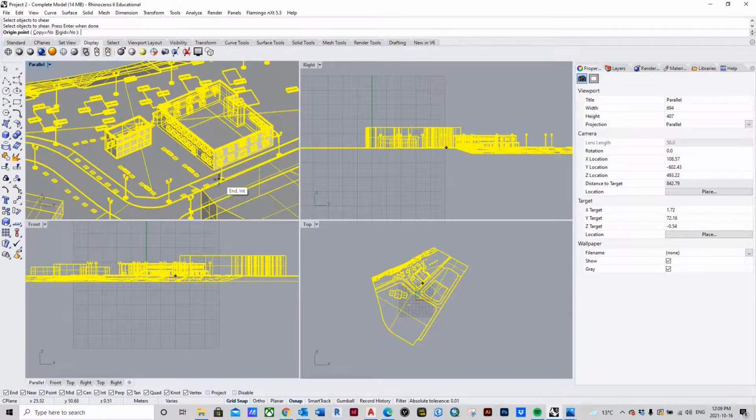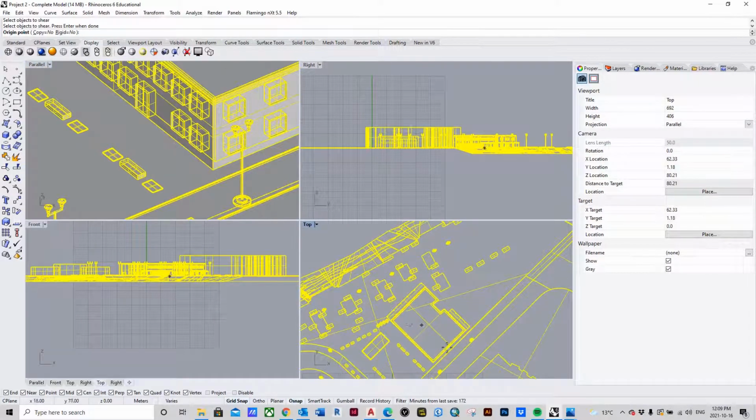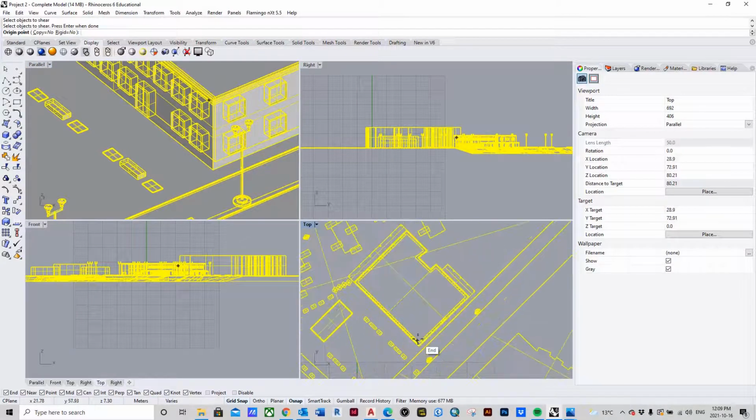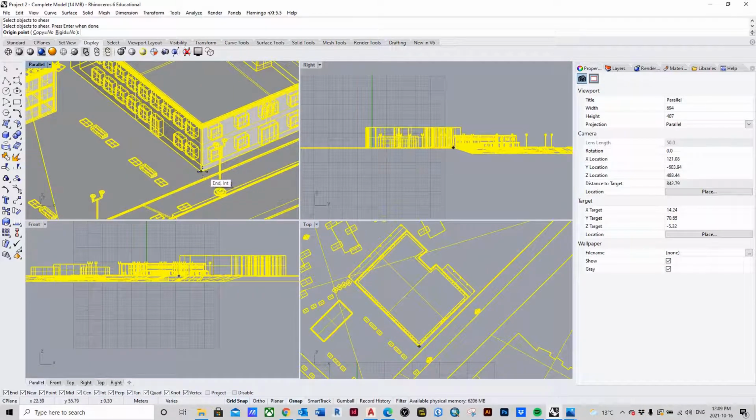I would personally recommend grabbing anywhere near whatever building you turned to get this plan view. I would recommend you grab it from the base point of that. So that's going to be the first point selected.